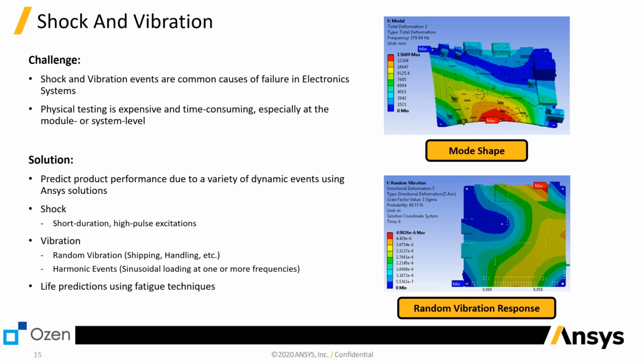If you put it on a truck, there is PSD excitation data, random vibration data for shipping on a truck. Then when you put it on an airplane, there's a different curve to do random vibration for plane transportation. There's even one for helicopters. So you can simulate all these events one after another to see if your sensitive electronic equipment is going to be affected by transportation, by shipping, by handling.